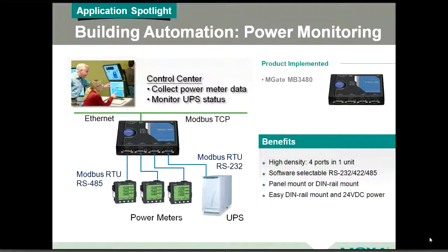One application, and I think you saw that power meter on here, is energy efficiency. We find there's a lot happening nowadays with folks looking at doing energy efficiency. To be more efficient with your energy usage, you have to know where you're utilizing that power. A lot of systems within building automation, and this even overlaps within plant floor applications, have your power coming into a facility and have your switch gear. It's gotten quite commonplace to instrument that with a 3-phase power meter installed within those panels.